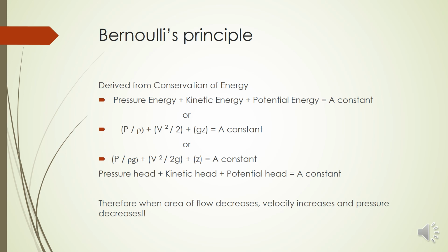So that means now we have come across the final answer of the first question. If the area of a flow or a pipe is decreasing, by the continuity equation, the area decrease means velocity should increase. Now you apply this in Bernoulli's equation. Here the area is decreasing, the velocity will increase.